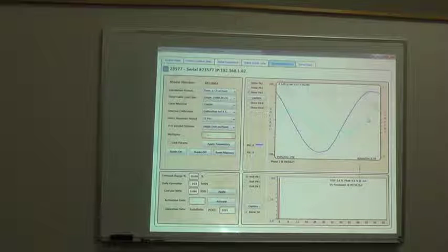Phase 3, well, don't forget, there's only 2 amps. Okay, so there's not much there. Right. This is 50 amps. So when you have a shape like that with 50 amps, you have a problem. This is the HVAC panel, so there's a lot going on there. This is the church. Well, don't forget, the peak on that is in the center of it. That means you have a special equipment that's causing that. Exactly.